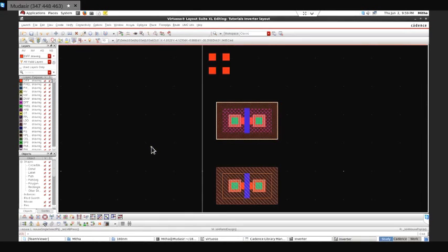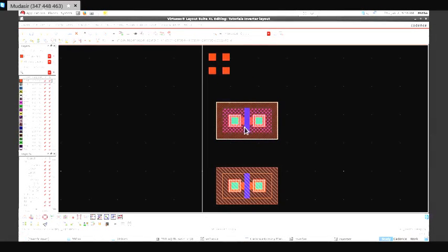As can be seen from this figure, the transistors are generated here and the pins are generated here. So these are different pins. Now this is okay for simple small circuits like differential amplifiers, op amps. Up to op amps it is okay, but when you go for higher circuits and you generate all of these at once, you will get confused about which transistor you have to connect, and it will all be in bulk, so a lot of confusion will be there. It will add complexity. So what I usually do, let's delete all these things.